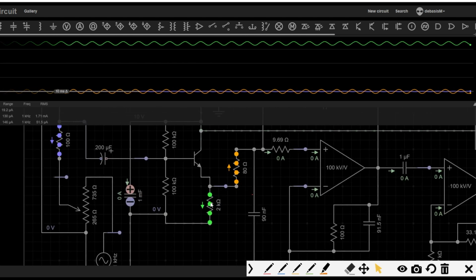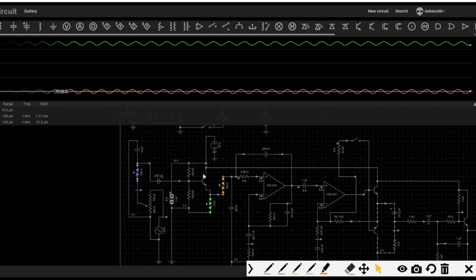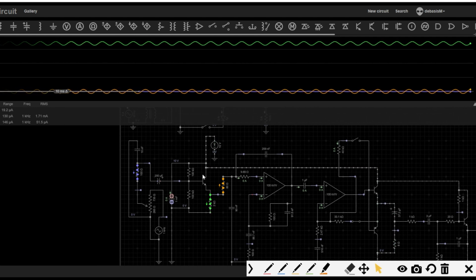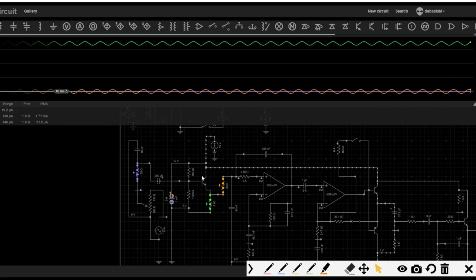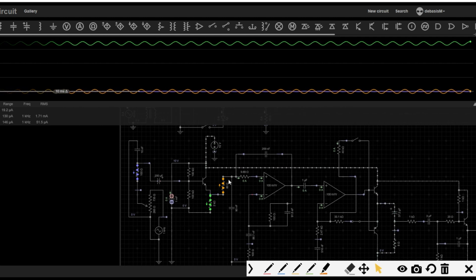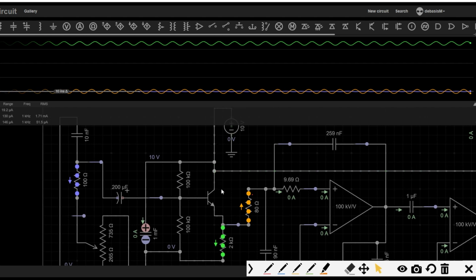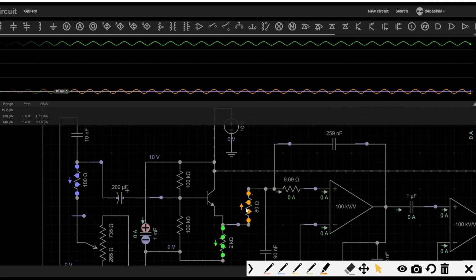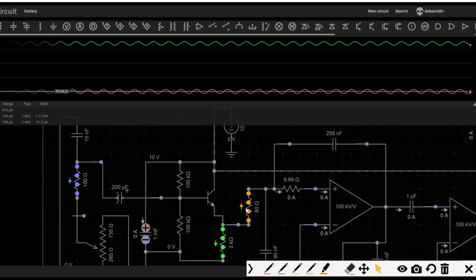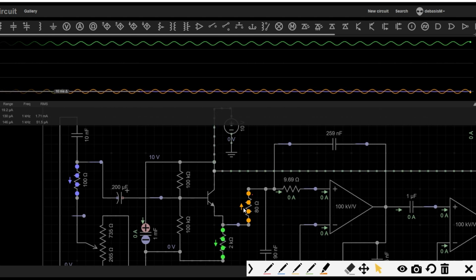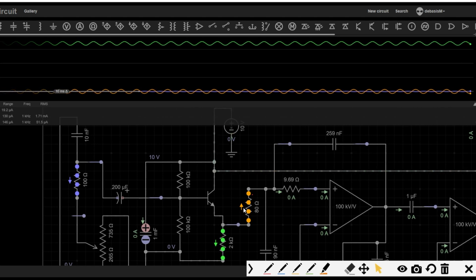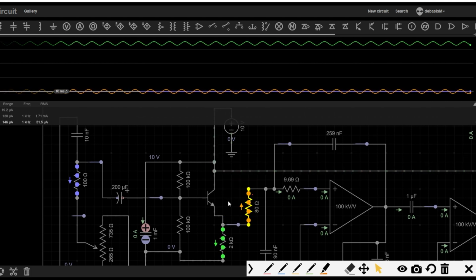Now if you go by theory, a single NPN transistor can also be used as an audio amplifier. So why are we not using it? Actually this transistor in this configuration is called a class A amplifier. There was a time when a single transistor could be used as an audio amplifier. The problem is that power consumption is very high, so the efficiency is very low. I think this kind of transistor can give somewhere around 50 to 60% power efficiency.